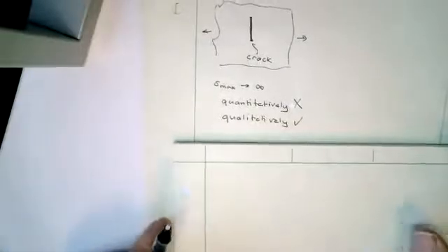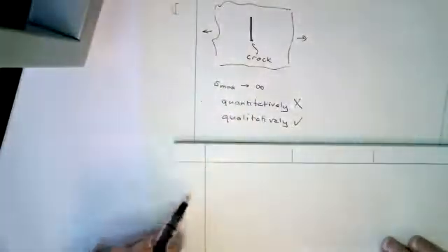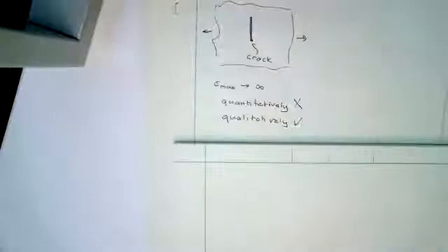But what's going on here? Why do we get this infinite stress? Well, it's the same thing as I asked you about when the hole closed. When the hole closed and you had it under, say, tension, you still got a stress concentration factor of 3.